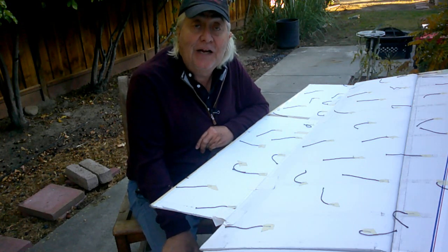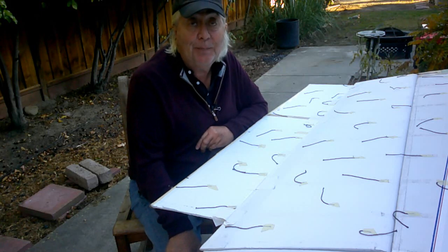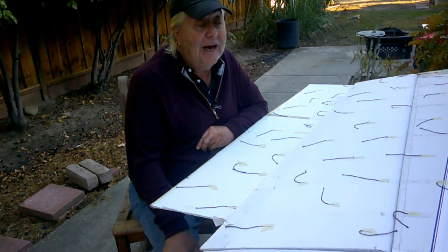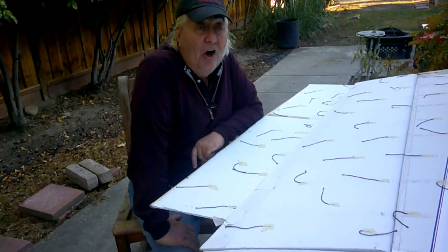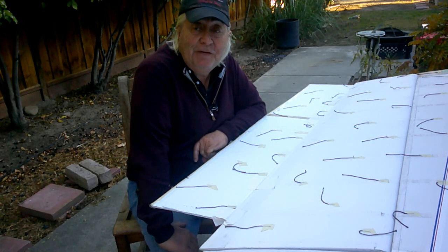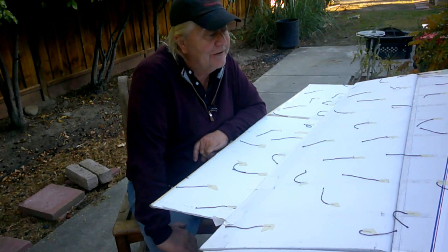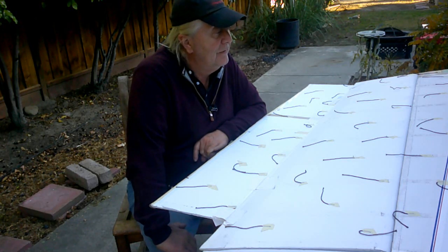Interesting way to do a design. Nowhere in all of my design efforts or training have I ever been taught to start with a tip chord and work from there. But that's how these things should be designed. You start off by saying, I need a minimum tip chord of 32 inches, and go from there. And as it turns out, at 150 square feet and 15 meters of span, 50 feet, well, darned if that isn't 36 inches, 3 feet. And you might as well just have a constant chord flying wing.